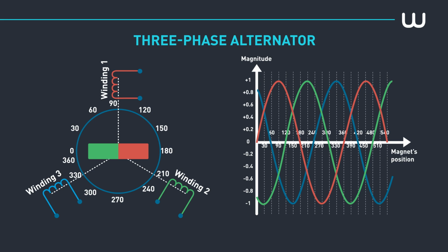During rotation, there are three sine waves shifted by 120 degrees, the frequency of which is linked to the magnet's velocity. Sine waves appear out of synchronization on the chart. This is called wave shift. As the North Pole cannot be opposite all three windings at the same time, this creates a shift of 120 electrical degrees between each sine wave.